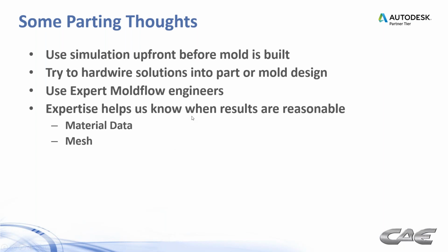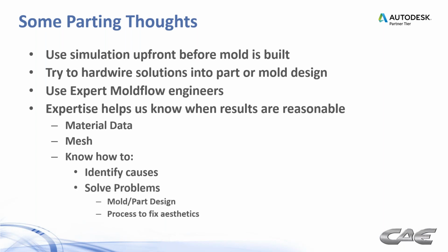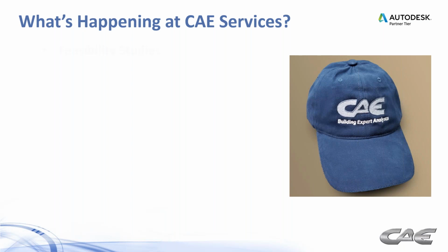You saw that knit line that was missed earlier because the number of elements they put on the Moldflow model was insufficient. The engineers are going to know how to identify the causes by using Moldflow, and how to solve those problems through mold and part design, or if it comes down to it, how to process it. So it's really important to not only use Moldflow, but know how to use Moldflow. Can't stress that enough.